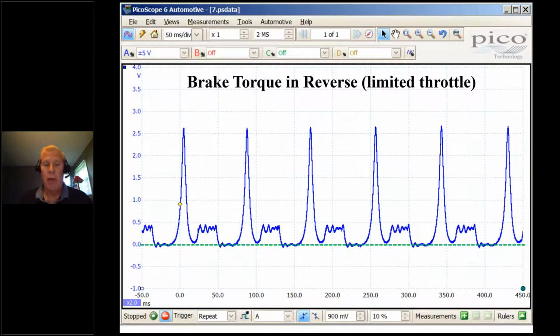Take a close look at my pattern and look at my 0. You see it? That 0.5 is 50 PSI. So those exhausts, this whole pattern has been elevated upward. And you can see my pressure, that's 250 PSI. So I'm moving some air in this cylinder, but that's about 40 some PSI of back pressure. And I tell you that just because, in some cases, especially if the restriction is further downstream in exhaust, you may have to create a lot of air mass to see the impact on your analysis.